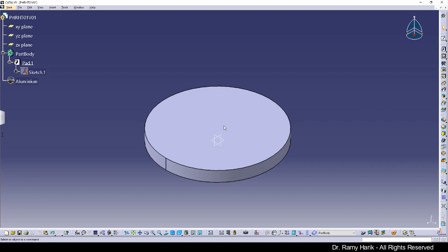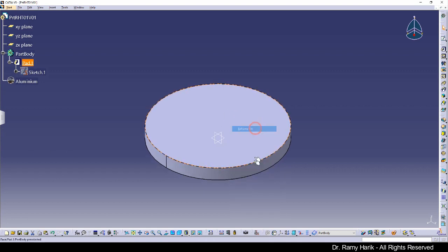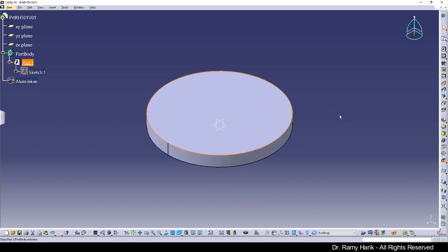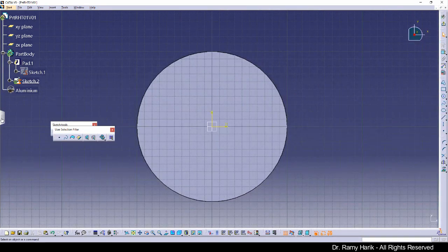So now going back to the tutorial, we are moving to the creation of a second sketch. At this stage, I'm going to reframe on my part. I'm going to select the top surface and I'm going to click on sketch again. At this stage, what you are being asked is to create an ellipse, and this ellipse will have a short axis of 120 millimeters and the second long axis at 160 millimeters. So we're going to come here and click on the ellipse feature.